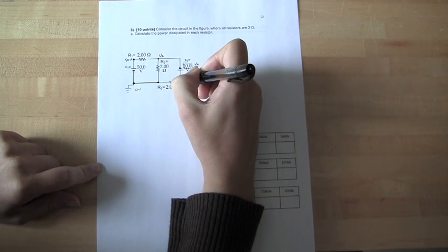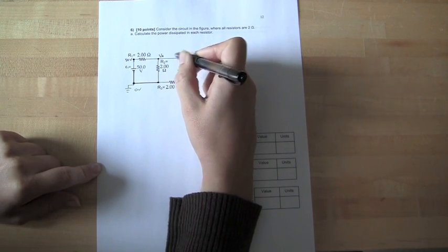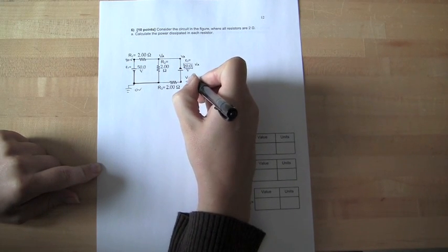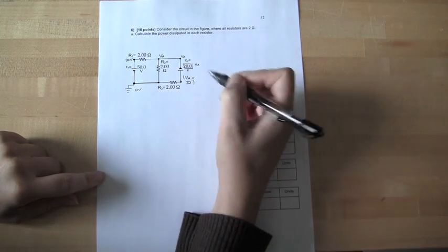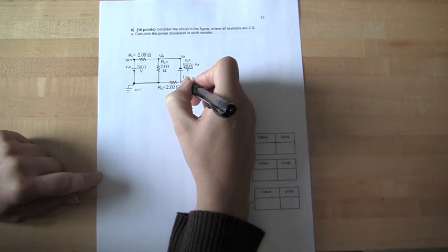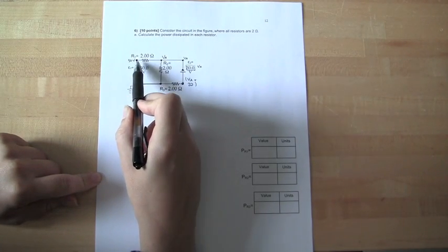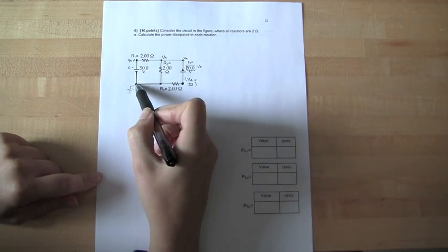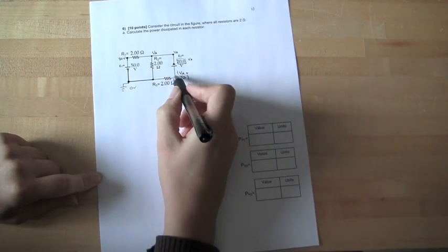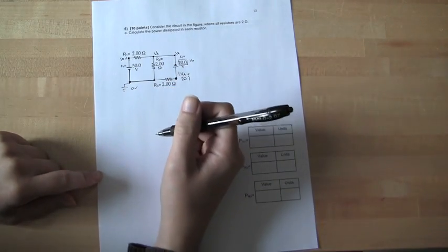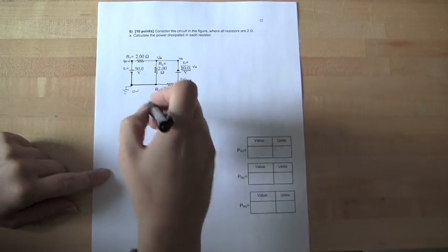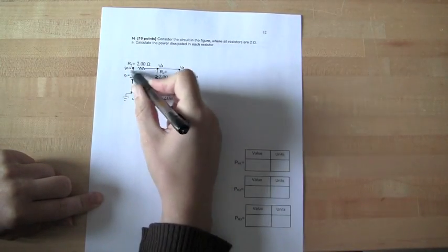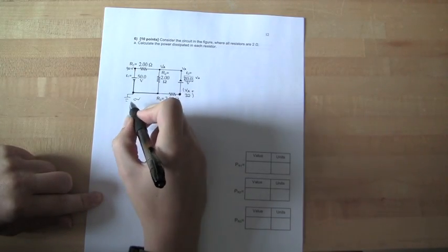So the other side of this battery is at VA plus 20 volts. So the battery is just adding 20 volts to whatever's on the one side of it. So there's 20 volts difference across this battery. So we know this is at 50 volts, some voltage VA, and this will be VA plus 20. And this one we know again is at ground. So now we know the voltages or have some relationships for every point. Now we can use Kirchhoff's current law and write some more equations relating these voltages, and then we'll be able to solve for the voltage at A, and then we'll know the voltages at any point in the circuit.